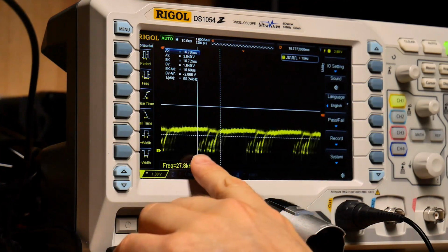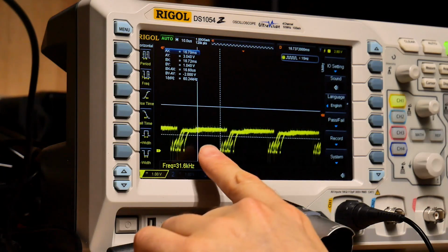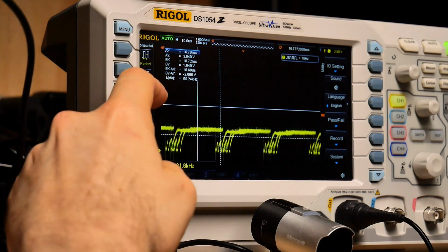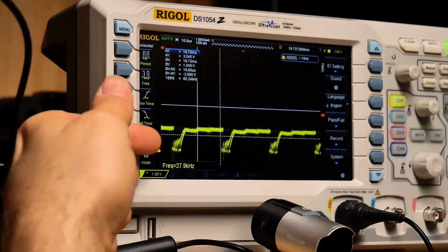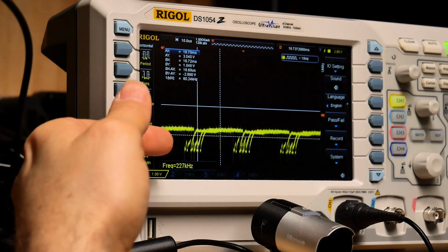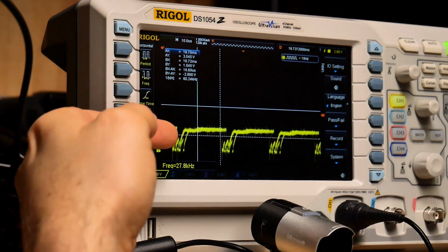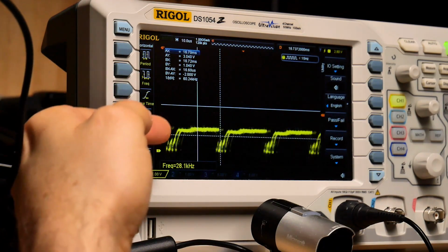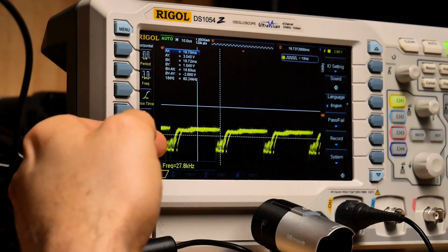Okay, so this is data line 5. This is not normal. Something's wrong on this data line. This is not going all the way up to 5 volts. It's lost trigger, which is why it's moving, but this is a problem right here. Something is definitely wrong. On this bus is probably the ROMs. There's a few components on it, right? And there could be many things that cause this particular issue, but there's definitely something wrong on the data bus, and that's going to prevent this computer from booting.